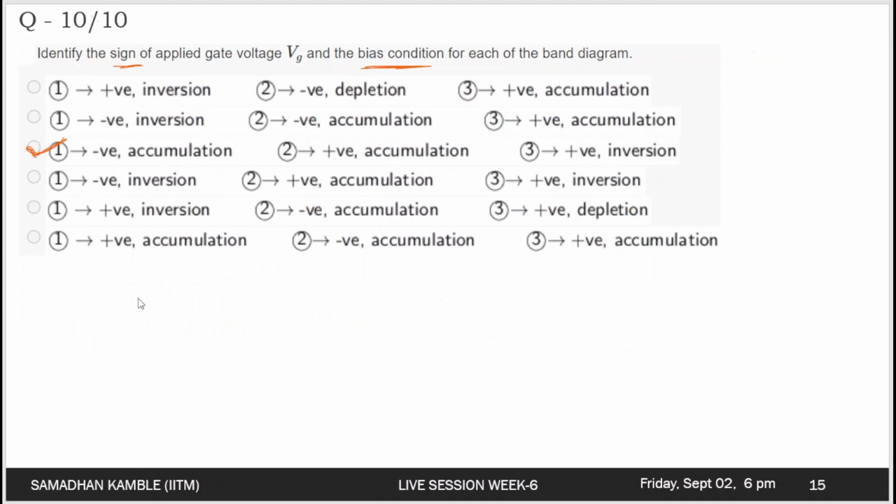But these are quite different. Their mechanisms are also different. One is because of the reverse voltage applied, and another is because of the higher kinetic energy gained by the charged particles, majority charged particles. So these are two different mechanisms. So what are you asking? Whether their energy levels look the same or different, whether their band diagrams look similar or different? Yeah. So their band diagrams for the breakdown